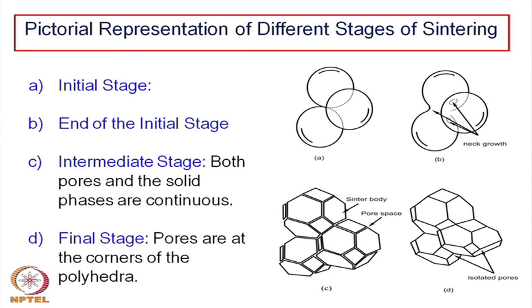So, as a result of mass transport and the change in geometry, the pores are not only becoming smaller and smaller in volume, the sizes are also becoming smaller, and from a continuous phase up to this intermediate stage they will be discontinuous at a later stage.